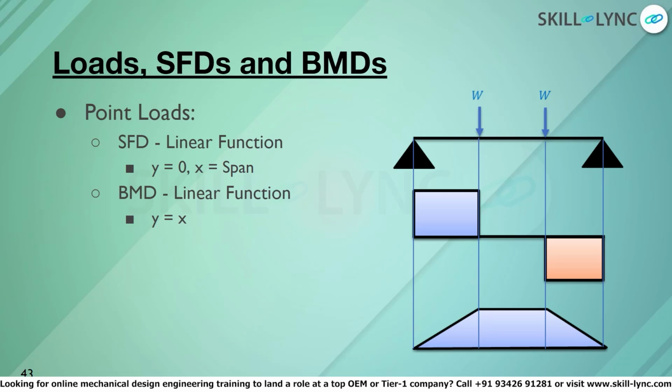So the first will be point loads. Let us assume that we have a simply supported beam on which two loads are acting. As for the shear force diagram, the point load will be depicted using a linear function where y is equal to shear force value, while x is equal to the span of the beam. Thus, the mathematical equation would look something like this, where y, the shear force, is at some value for the entire span until there is a change in the value.